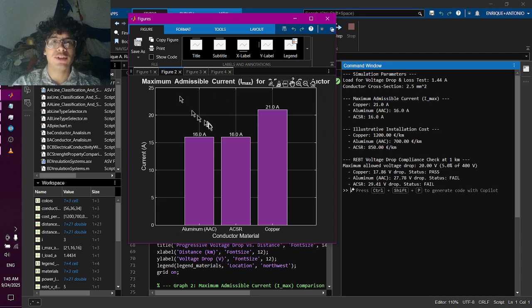The admissible current for the aluminum and the aluminum steel composite is the same, which makes sense as in both cases it is aluminum, the main conductor agent, and because of the skin effect, one can assume that most of the charges are concentrated at the edges of the conductor, so it makes sense that only the aluminum will be conducting and not so much the steel.